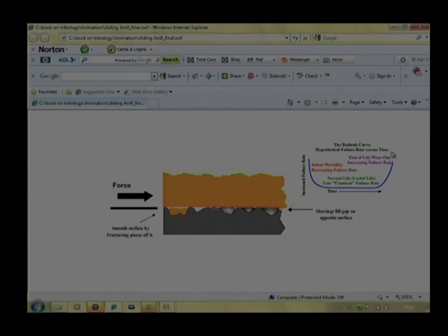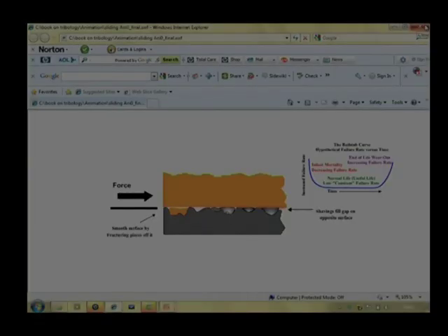So, we are more worried about this end part to estimate what will be the life of the component, and we are more worried about this steady part, which is going to tell when the component is about to fail and what will be the maximum life which we can achieve from this. And this is a hypothetical curve; not every wear curve will be like that. There is a possibility of continuous increase in wear rate, and it will never be in a steady state condition. That is why we need to understand wear mechanisms properly.